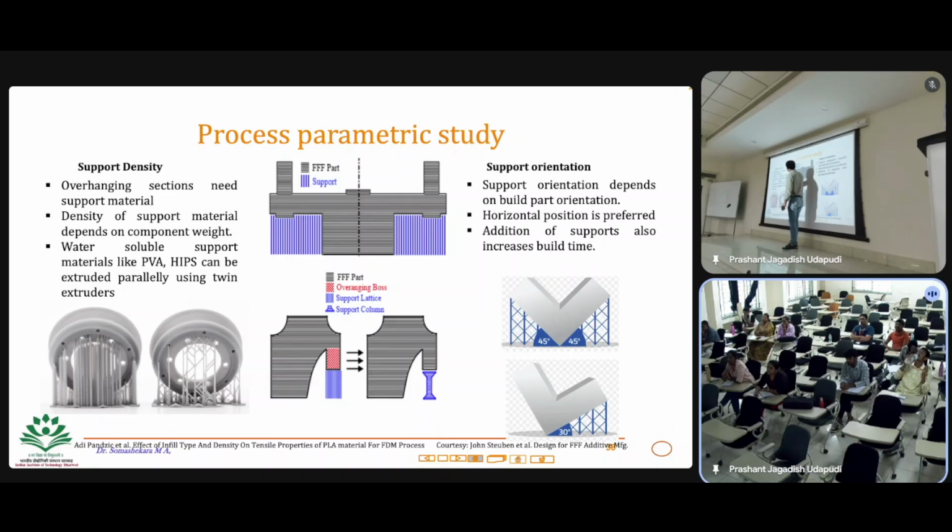Because without this, you cannot print, because it is almost like a 90-degree angle. Before you start the printing, you will be able to print to some extent, maybe partially. You can extend a little bit of support structure from the material you have already modeled, up to maybe here. But if you go further, the material will simply fall. But you can take advantage of the previous layers.